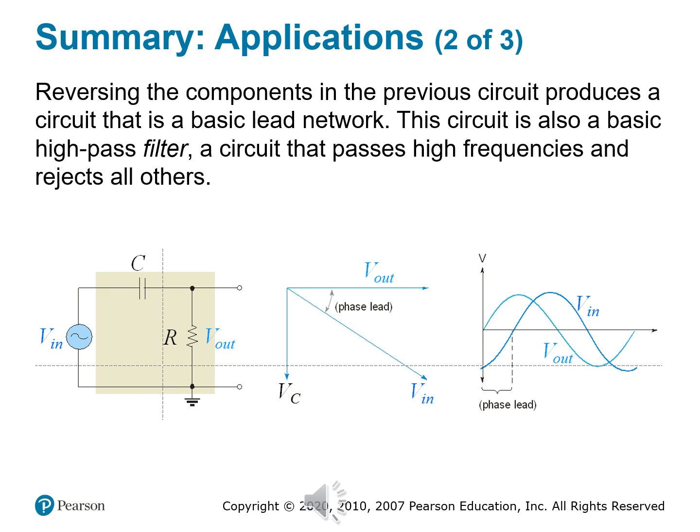When we're talking about high pass filtering in action, this is where things get spicy. Again, whatever it takes to make this interesting for you. At high frequencies, the capacitor acts like a short circuit, and the resistor gets the full signal. At low frequencies, the capacitor acts like an open circuit, and voltage out drops to nearly zero. So what are we left with? A high-pass filter, the exact opposite of what we had in the last configuration.